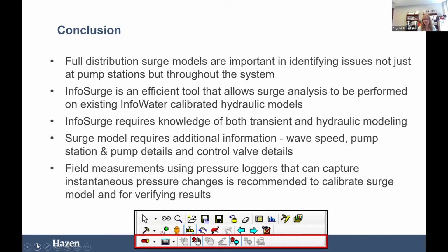It's calibration. It also helps to make sure that the mitigation devices we're recommending are reasonable and cost efficient, because if we don't calibrate the model, the model could be saying much larger issues than are really there. And so we could be oversizing things, which won't hurt the system, but could just cost the client more money. So if we calibrate, we can give better results and also give the client better costs in the end.